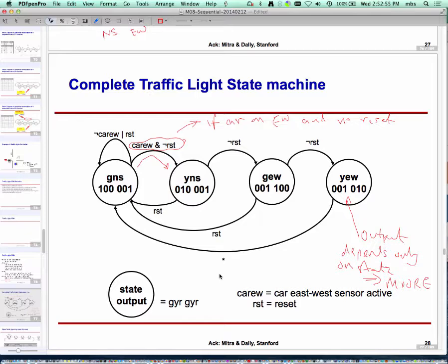Some of you may have used MATLAB and these kinds of tools in some courses. They have these kinds of packages built in. You essentially draw the state diagram and it can generate stuff for you. There are lots of commercial tools. In the book, you have probably noticed the Verilog examples. You can write a state machine in a programming language like Verilog, so that's also possible.